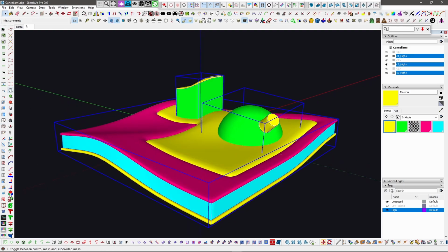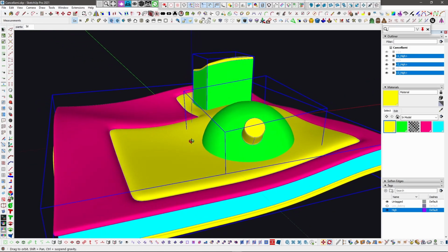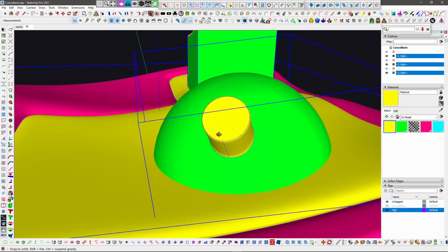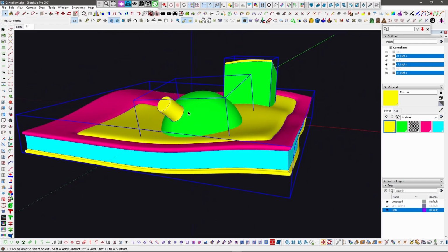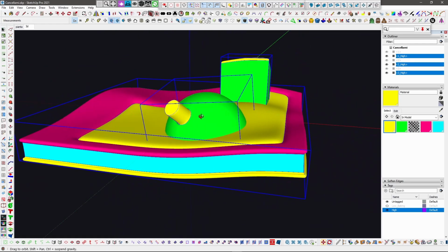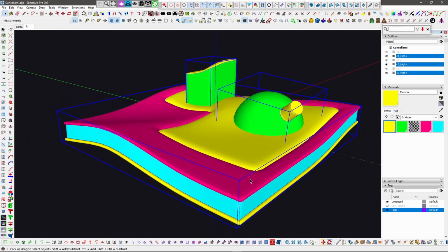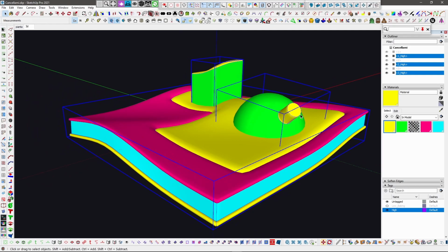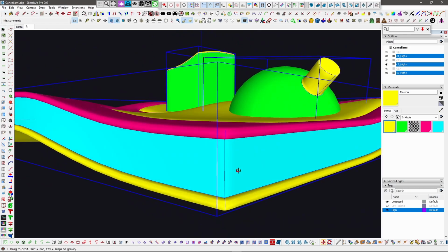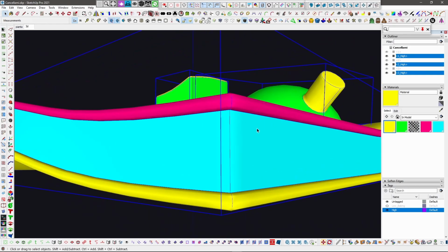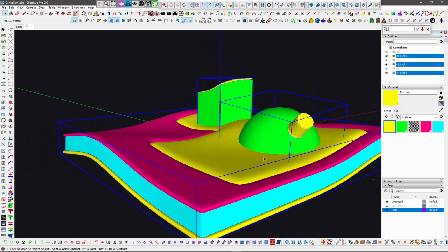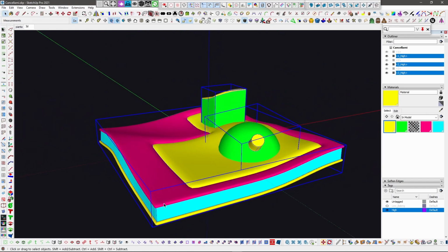And if you want, you can subdivide this a bit more so that it will bake a nicer normal map, maybe. But in this case, I will keep it simple. I will just use this for ID because I should manage the creasing, a lot of stuff to create the proper hi-poly for that one.